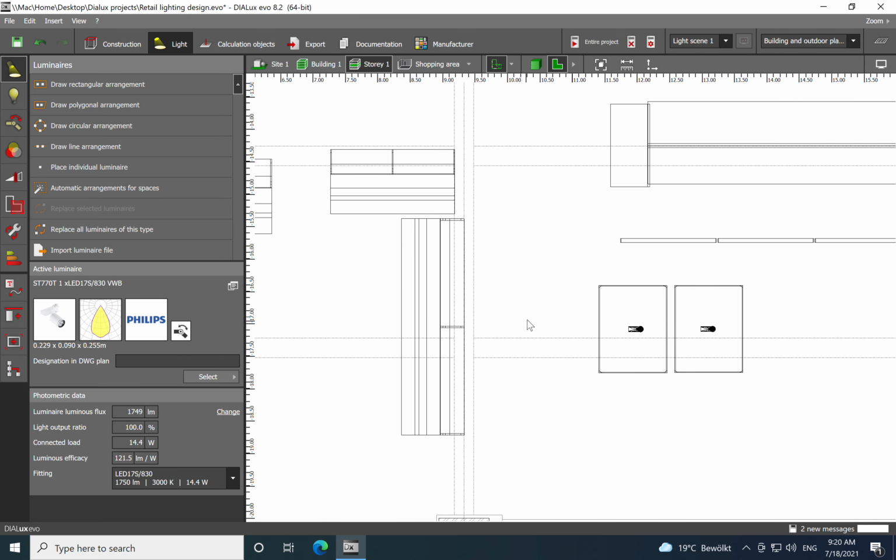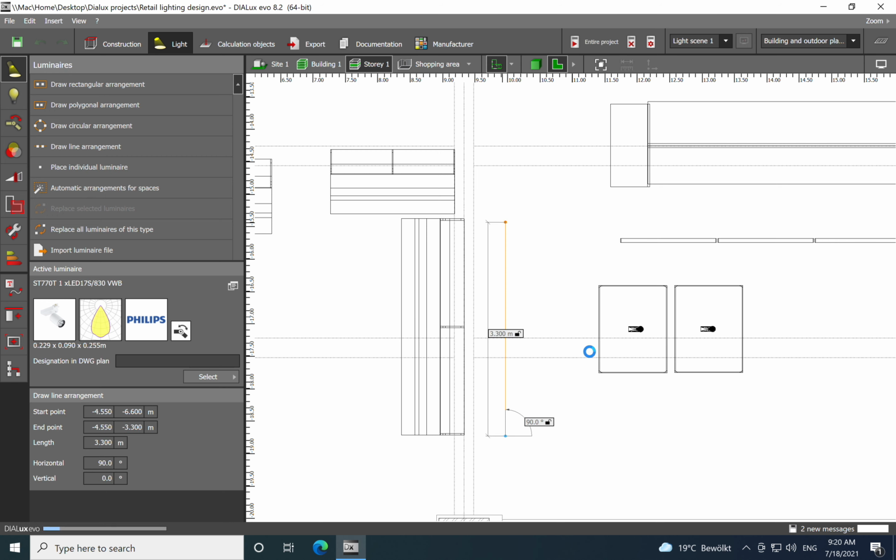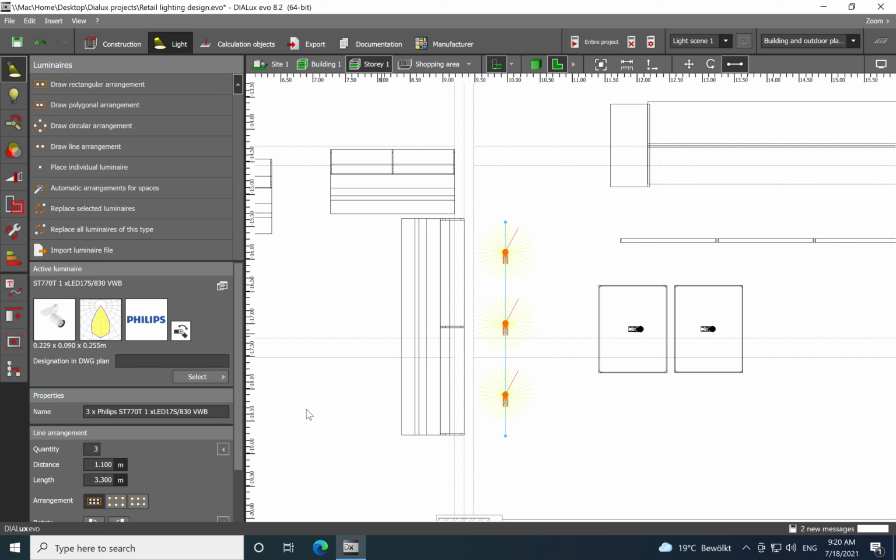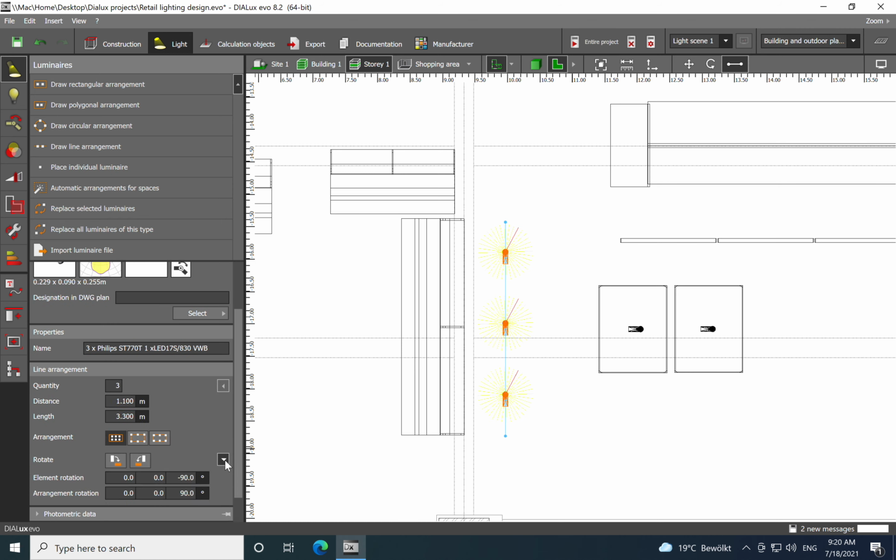But the main point is to see how I'm doing, to get the point of what the main criteria are when you establish these luminaires, which type of luminaire is being used, how you run the calculation, and why you need to use, let's say, on the projector different white beams, different CCT, and how to combine the 2 solutions, like continuous line, where it makes sense to use it, and where you should use the spots or the projectors in that space.